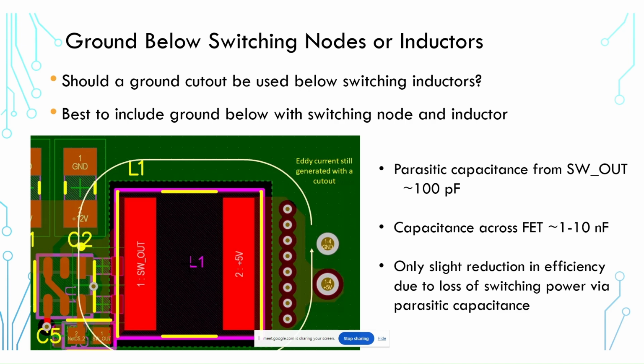So shielded inductors, especially in this package format, are very common. You can get them from Würth, you get them from Pulse, you get them from Murata. All sorts of different vendors provide shielded inductors, with very marginal additional costs. So I recommend going that direction.